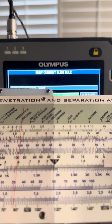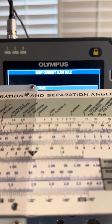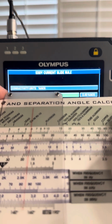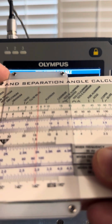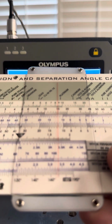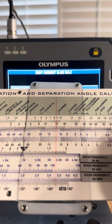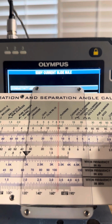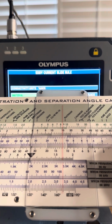So let's just imagine a 1% flaw out there at 170 degrees. Instead of going to 1.1, you'll just move this red hairline, and now we're going to use the bottom scale for separation angle. We'll put that over to 170. And again, this is all ballpark. It gets you close, and then once you dial that frequency into your instrument, you can fine tune it, adjust it, and verify that you're seeing what you expect to see.